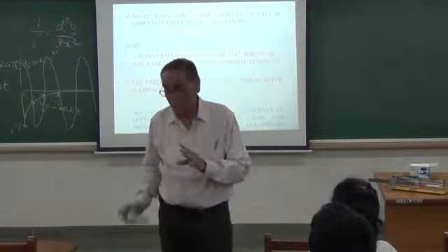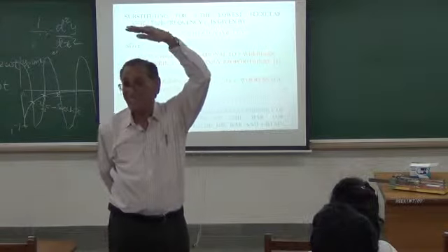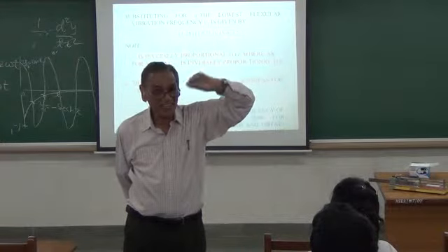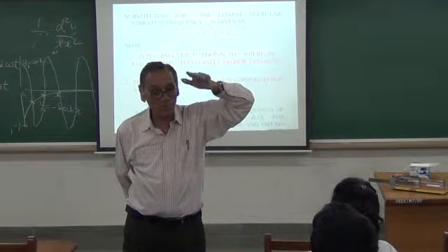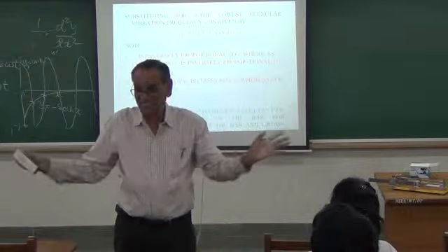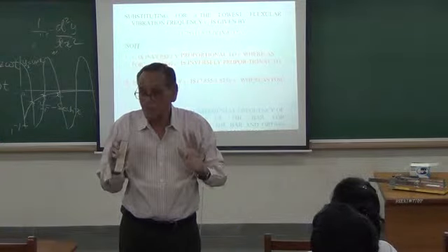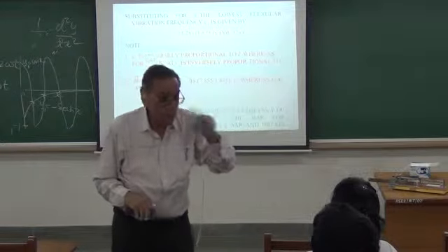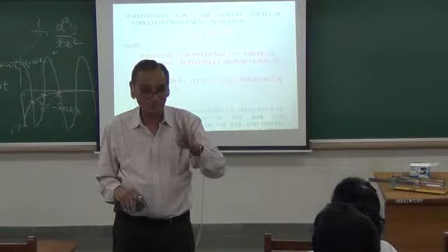So to find the resonance frequency, start at a very high frequency, close to 100 Hz. Reduce the frequency slowly. When you get the first resonance, that is the omega naught. When you get the second resonance, note the frequency multiplied by 2.